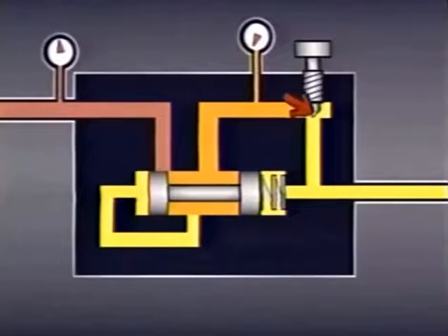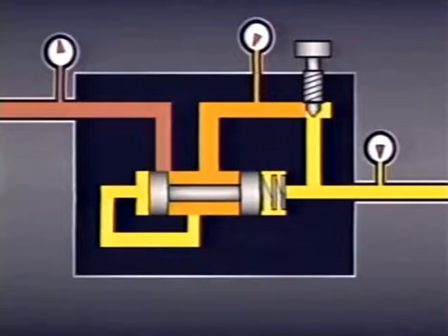carried away as heat. As long as there is no load, the pressure just downstream of the restriction will equal the pressure of the spring. The difference between this pressure and the inlet pressure is always converted into heat. However, there usually is a load at an actuator when the system is operating. Changes in the workload create pressure fluctuations downstream of the needle and also affect the flow rate. These fluctuations are compensated for by the other pilot passage. This passage connects the spring side of the spool to fluid pressure downstream of the needle.